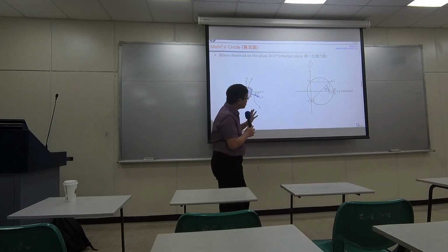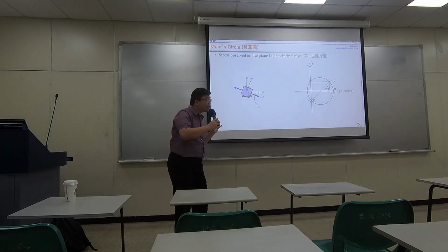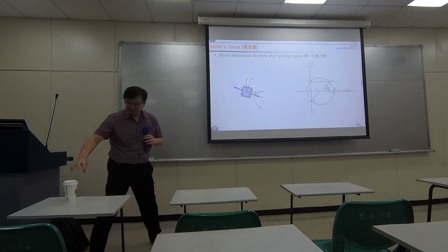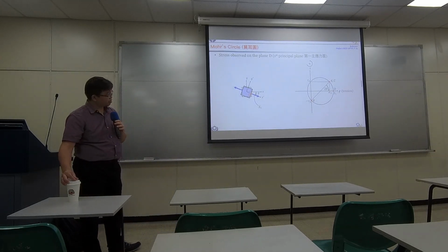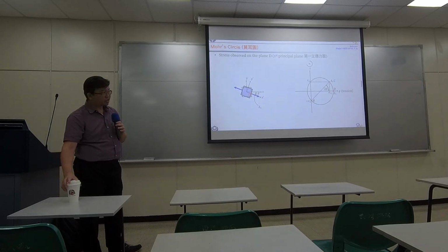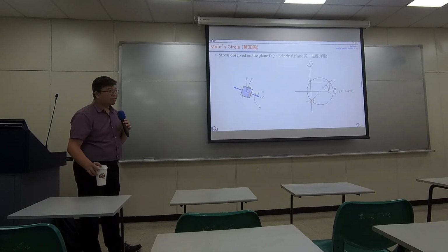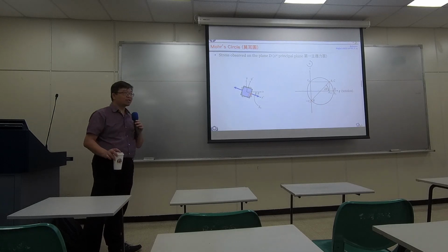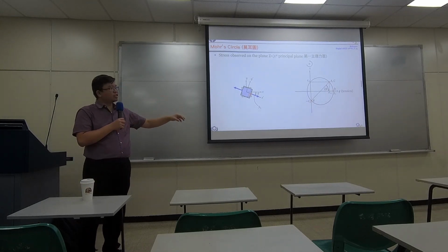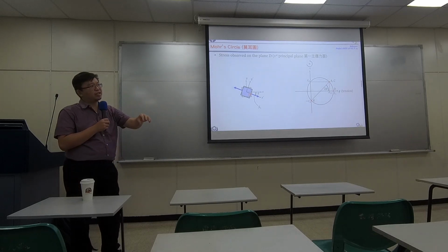If you observe the same material in a different orientation, you could have a greater stress. If you have greater stress, then that probably is a better coordinate for design. Because in design, we want to say the worst loading condition cannot be greater than how strong I am.